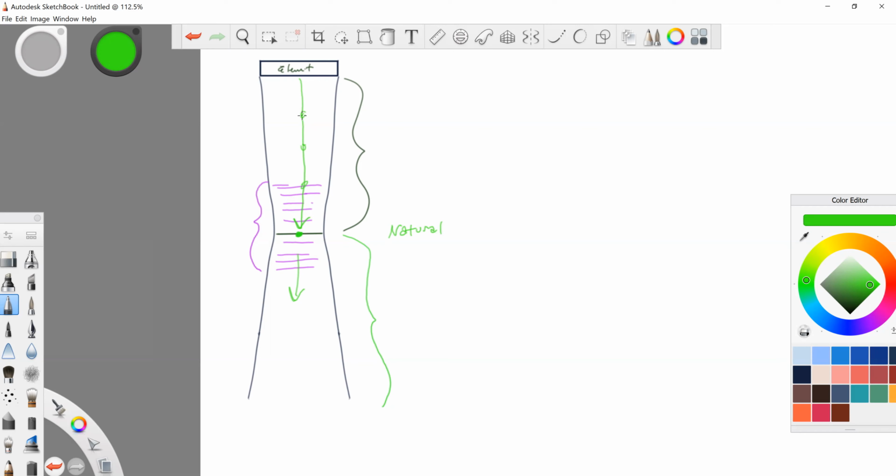You can change the focus either by external focusing, or internal focusing, or even with a multi-element transducer, electronically focusing. You can only bring the focus closer. You cannot focus in the far field. However, most elements are designed so that the natural focus is quite deep, so that you never really have to focus in the far field.